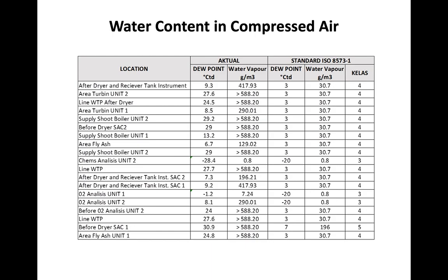But in actual, we find that this point after dryer is classified as class 4, with dew point 9.3 degrees Celsius.